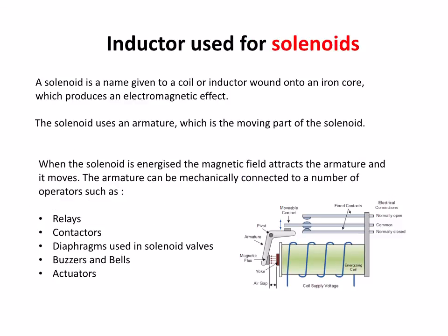It can also be used in a solenoid, so we can energize the inductor, it becomes magnetized, and it can pull an armature towards it, and that armature can act on something that will make or break a circuit. This kind of thing is used in relays, contactors, solenoid valves, buzzers and bells, and actuators. So we use the magnetic properties to form the circuit to make and break contacts.